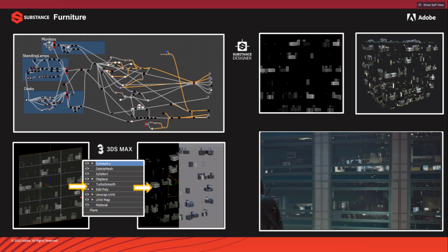And then you have full control. One thing that's really important is getting the pivots right, having control over the pivots and the scale of the objects. When you're trying to bring in assets like a bunch of desk assets, from arch viz, all the materials are separated, you're putting textures everywhere, and you end up with so much stuff at different scales. Everything has to be collapsed and reset and centered, and the pivots moved. It's just a lot of work.